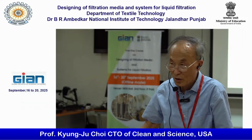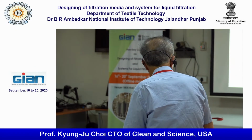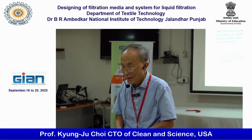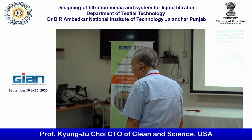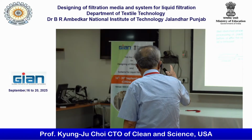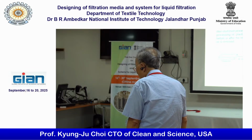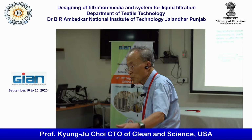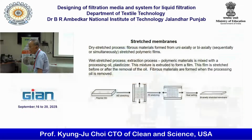MDO is machine direction oriented. Then we have to use the so-called tenter. I'm going to show you later. And then you can obtain the biaxial stretch film. I don't know why they call it dry stretch, because the polymeric material you have to melt and make into sheets or films, right? But they still call it dry stretch.